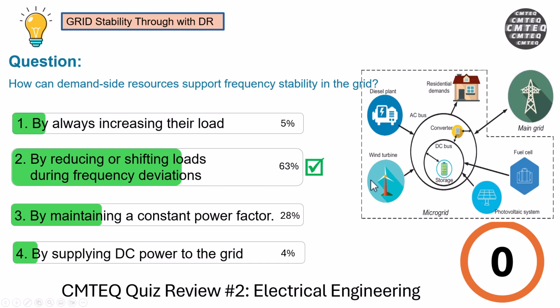the grid. So it's basically a cost effective decentralized solution that improves grid flexibility and reduces the need for spinning the generators harder using the reserves in the modern grid. So that's basically how the demand side resource or the DR system helps manage the grid stability by constantly interacting with the consumers to ensure that whether it's for frequency stability or just trying to flatten the peak demand when it happens. Great. Now let's move on to the next question.